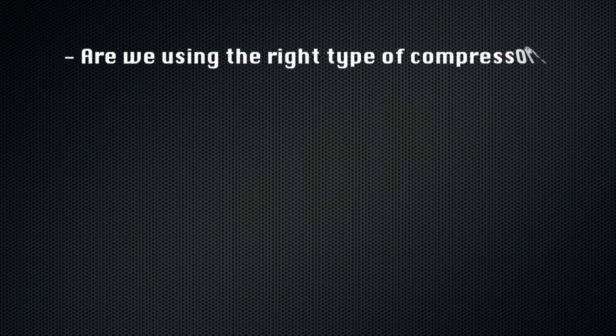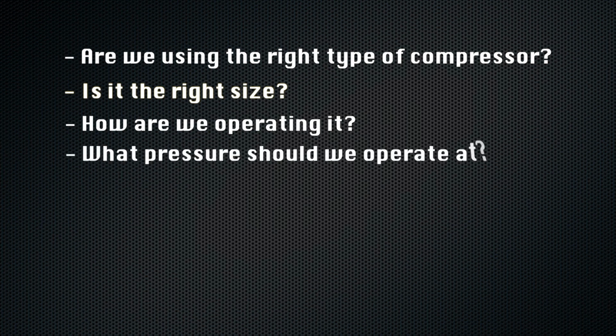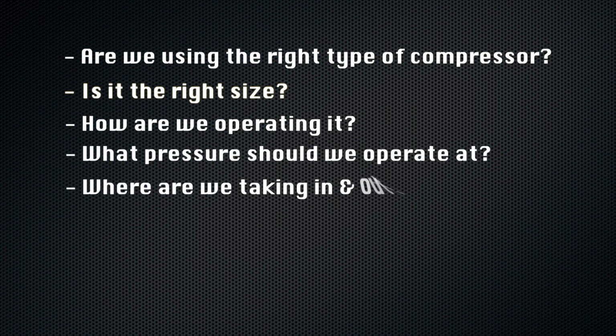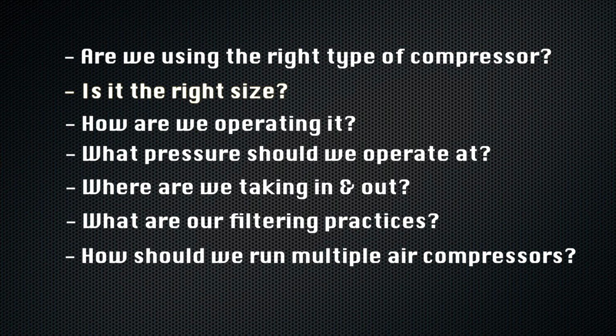Let's talk about some supply side opportunities you should take advantage of. Here are the questions we must answer. Are we using the right type of compressor? Is it the right size? How are we operating it in terms of load and unload? What pressure should we operate? Where are we taking in and out the air and the exhaust? What are our filtering practices? And how should we sequence the use of multiple air compressors?